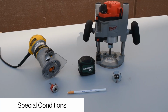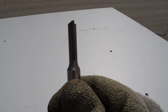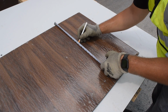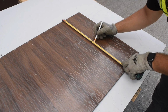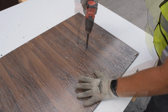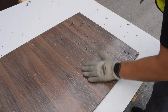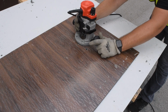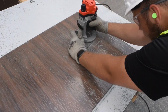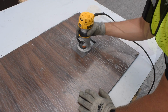We will now discuss some specialized field fabrication scenarios that you may encounter. The final process we will be covering is penetrations. When cutting out penetrations, it is important to measure and mark out the desired size. Once the penetration has been measured and marked out, start by drilling a minimum 5/8 inch hole in the corners of your penetration. Next, slowly work your way around the perimeter of the penetration with a hand router using a plunge router bit. Remove the cutout section and finish by chamfering the routered edges.